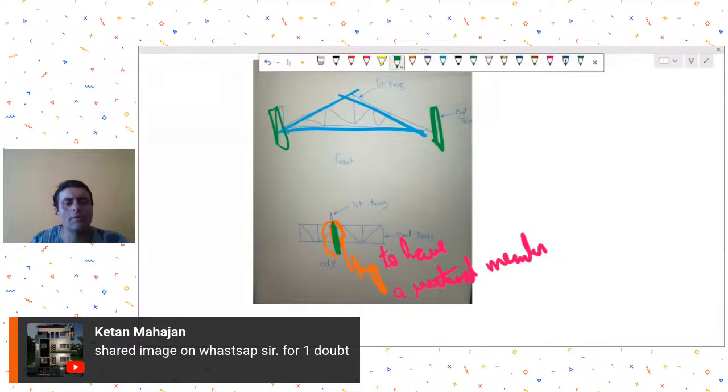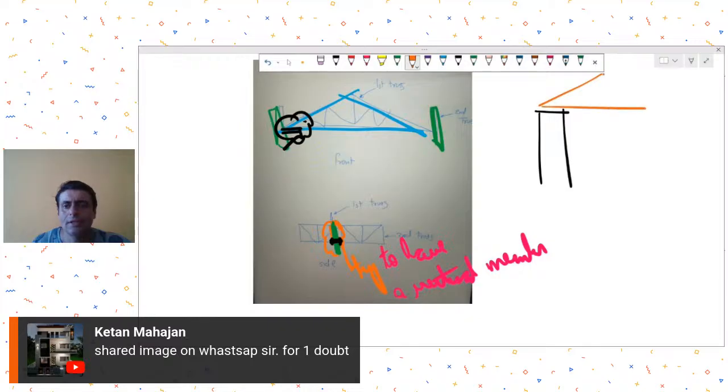Then from this vertical member, now there can be different options. One of the options can be that you can have a bracket taken out from this vertical member of the second truss, and on that you can create a connection for this first truss member. So generally on the top of a column, your first truss would have rested, under normal situation.